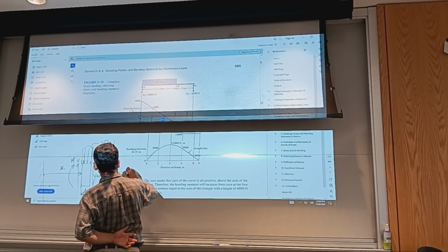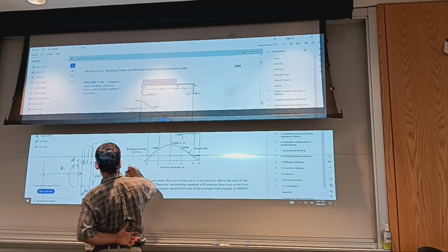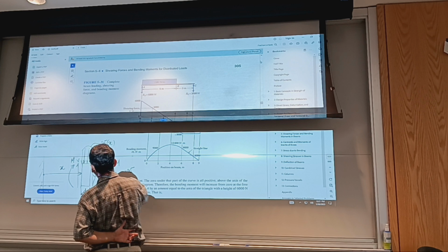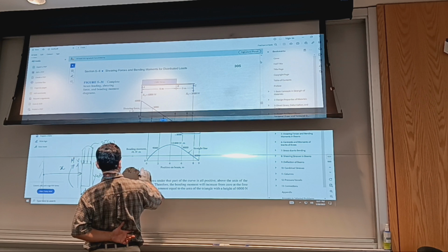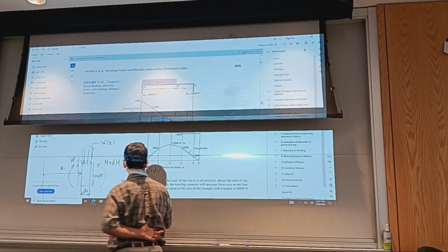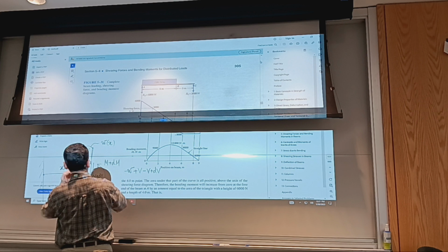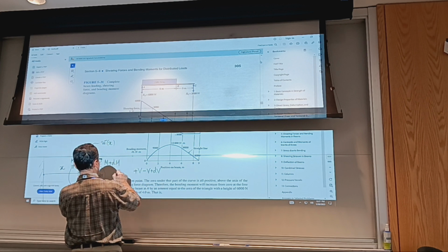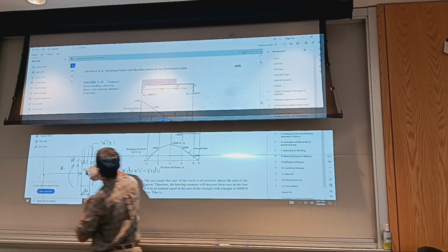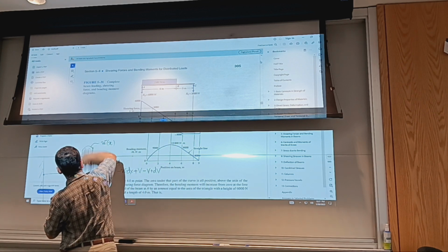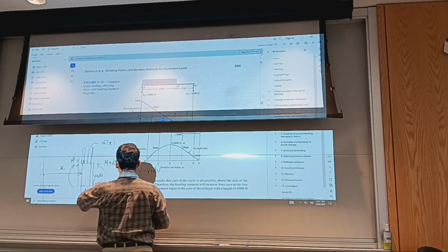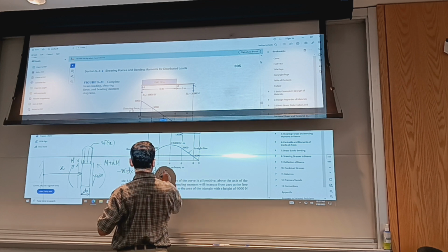So we'll say negative w, and then I have plus V, negative V plus dV, okay? So I wrote the equilibrium, and this will be w times dx, the resultant of this piece of distributed load going down, this V positive, this other piece negative, equals 0.